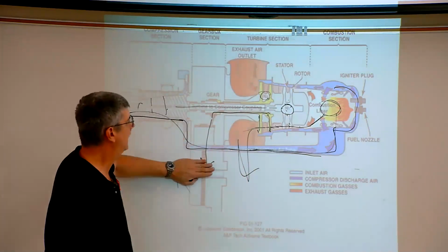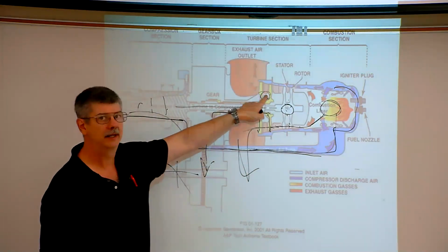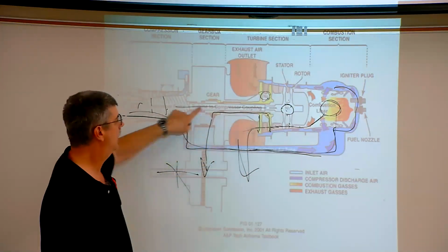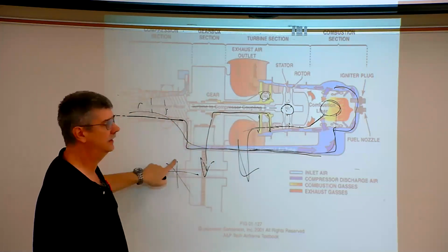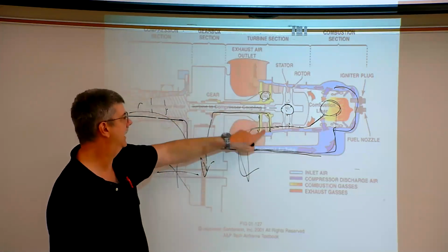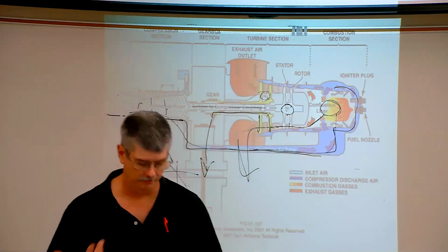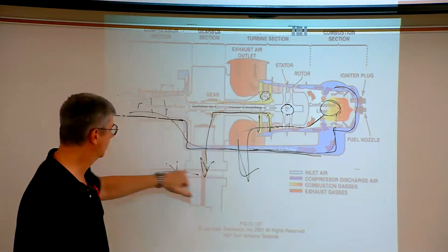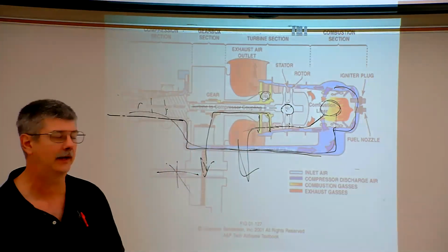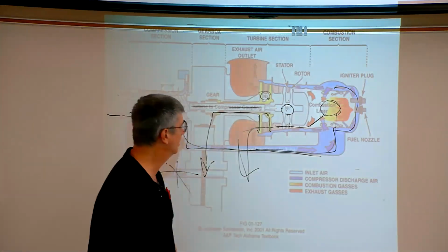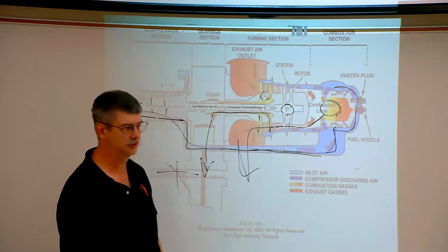We can hold that stationary, and the engine can run because N1 is not locked up and turns the compressor. When we release the rotor brake, then N2 can start spinning and put out the power. Usually this goes to the transmission, but it's known as a free turbine. The reason it's called a free turbine is because this turbine is free of the engine.